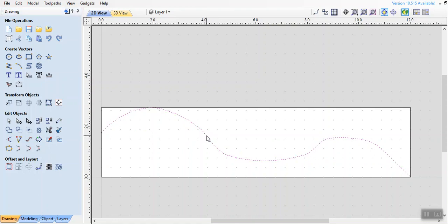I'm going to click on the spline and press the shift button. I'm going to click on the other three lines I earlier created. Now these four lines are selected. Now I'm going to join them where they meet at the same point. At the join command, click on it. So this way, I actually created four lines together in one piece.